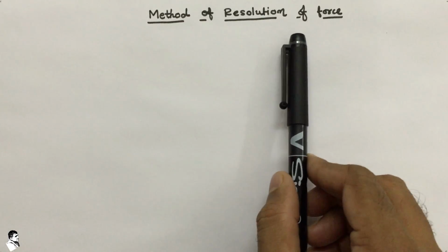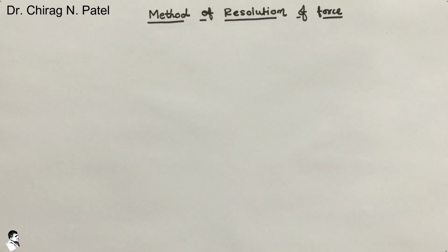Method of resolution of a force. The process of splitting up the given forces into a number of components without changing its effect on the body is generally called a resolution of a force. Now, a force is generally resolved along two mutually perpendicular directions.